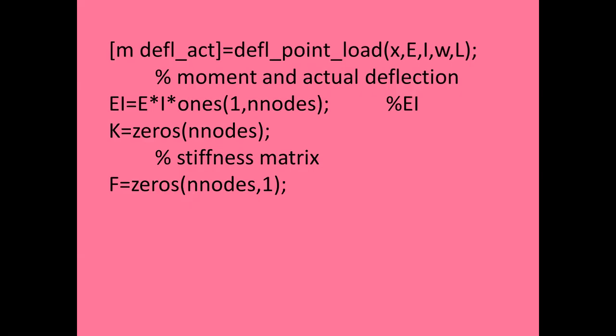So kindly note that in Matlab, a command can be used in more than one way. It depends upon the number of arguments which are given to it, and it also depends on the number of outputs which are going to be at the receiving end. In this particular case, when there is only one input, it creates a square matrix, and when there are two inputs, it creates a 2D matrix corresponding to the number of rows and number of columns which are specified.